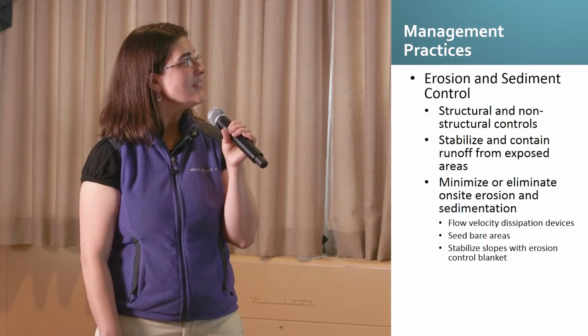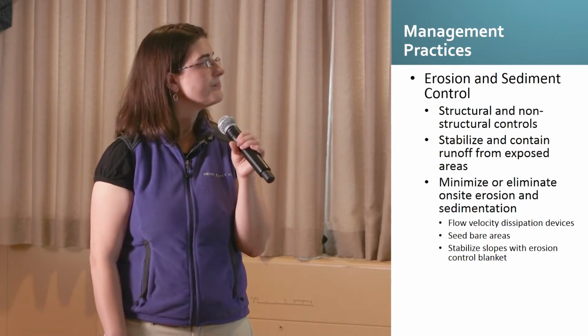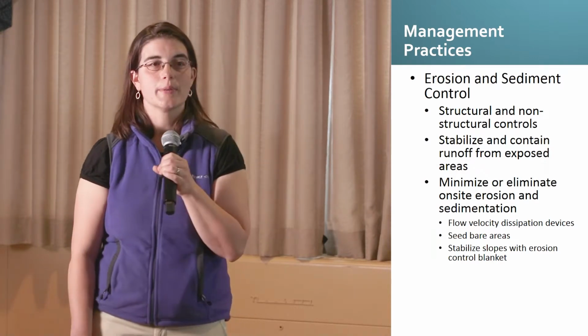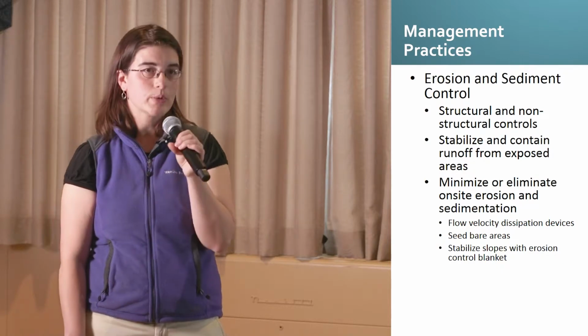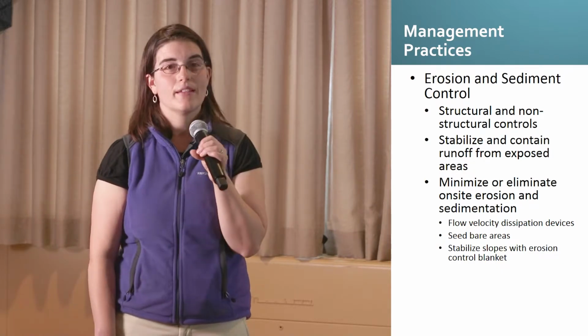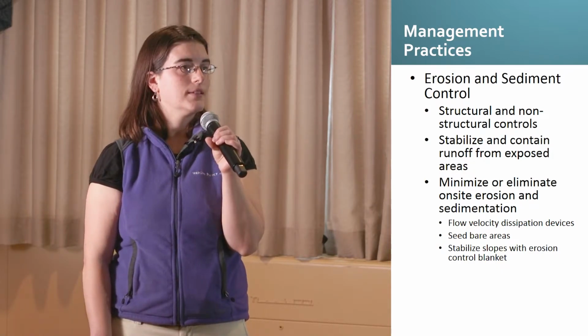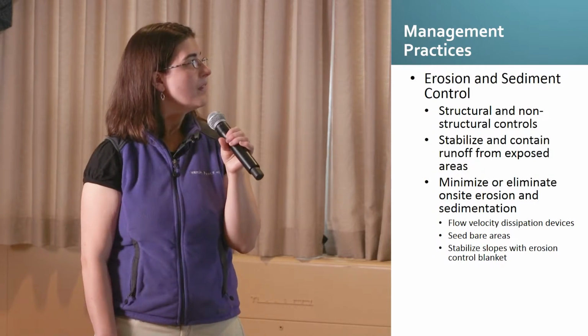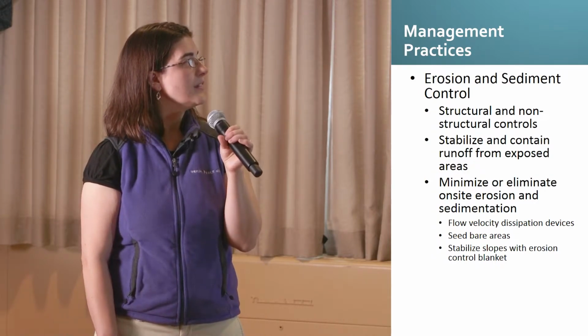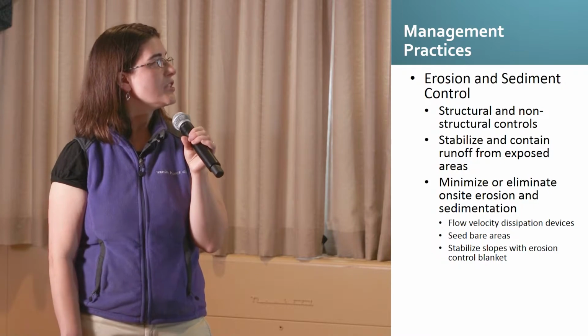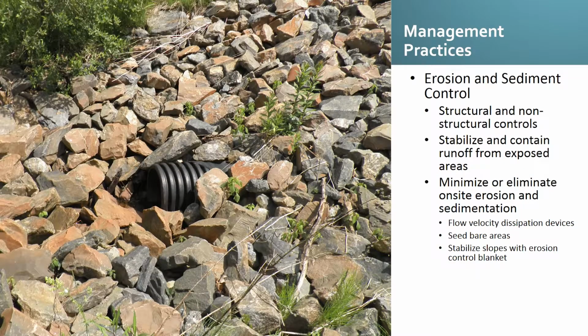Another management practice is erosion and sediment control. These controls could be structural and non-structural controls to prevent sediment from leaving the facility. So you want to minimize or eliminate on-site erosion and sedimentation by stabilizing and containing the runoff from exposed areas.